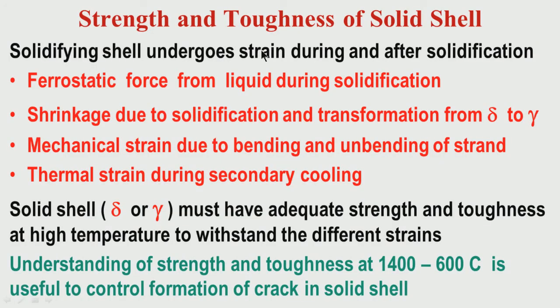Now, what are the strains? Let us try to see. During solidification, there is a ferrostatic force from the liquid which is still there during solidification. After solidification, there is no liquid, there is no ferrostatic force. But during solidification, there is a lot of liquid. So, the ferrostatic force from the liquid will push the solid shell towards the mold. So, there is some strain on it, number one.